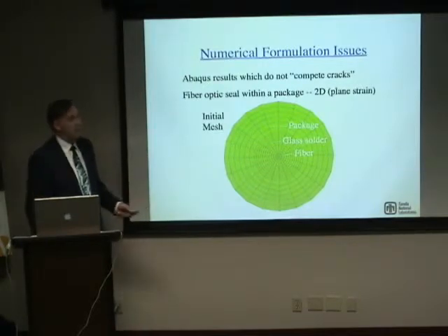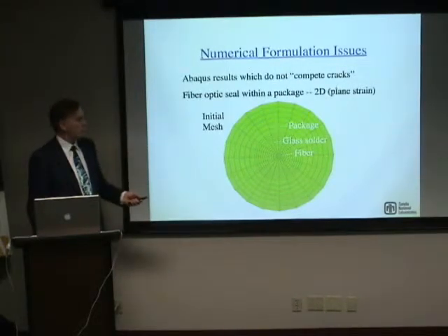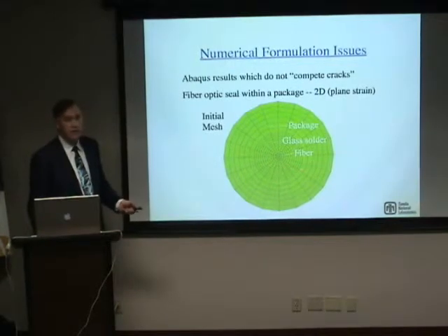So we take this thing up, and I didn't describe it earlier. We're coming down from, say, the glass transition temperature, we're cooling down from that point. And so all we're doing here is looking at a problem that's isothermal. We're slowly bringing it down, and we're looking at whether we're going to crack the glass solder as we cool this down.